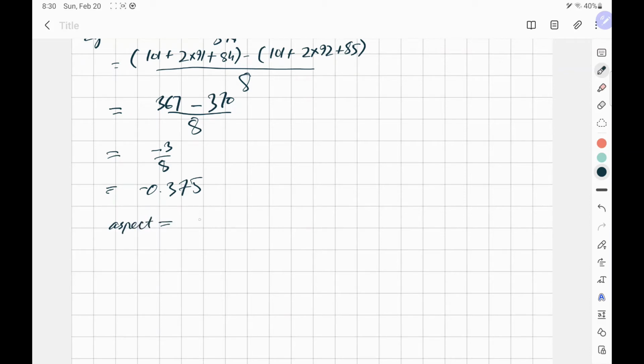It is equal to arctan2 of slope in y direction and then minus of slope in x direction, and whole multiplied with 180 divided by pi in case the value is coming in radians.